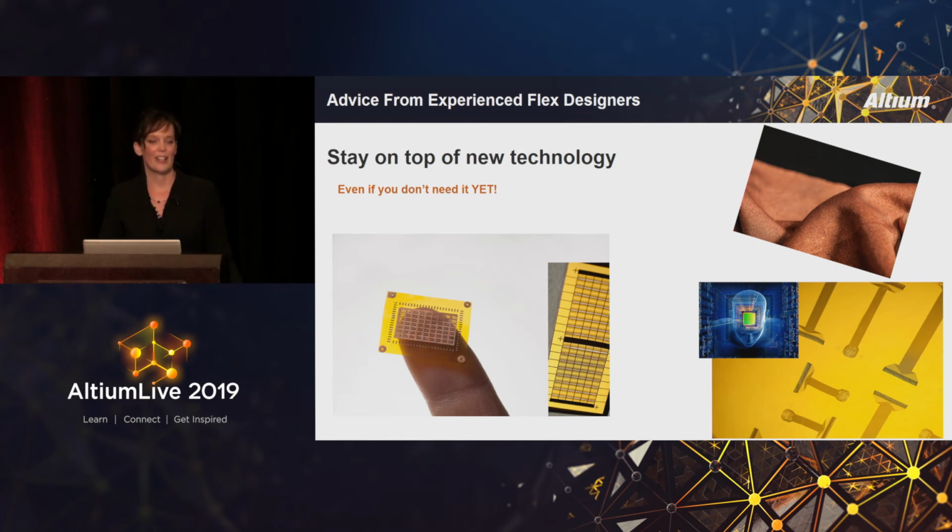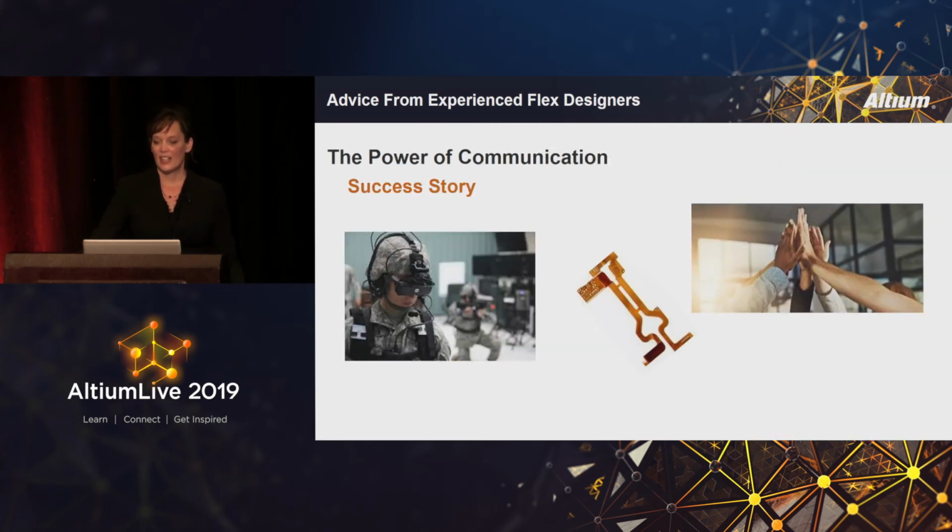The iPhone 10, I think, teardown had the 30 micron trace in space being done with modified semi-additive processing. That's in high volume offshore. There's a semi-additive process that is gaining momentum here in the United States for low volume development type stuff, and that's able to go to 25 micron, even down to 5 micron trace in space. So it frees up a lot in terms of routing, number of layers, number of lamination cycles that you need, not to mention form factor. We're doing things on tips of catheters, neural probes. It's going to be probably a game changer in the next few years, just having that ability and added benefit.